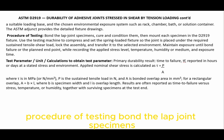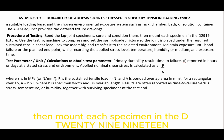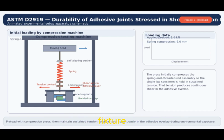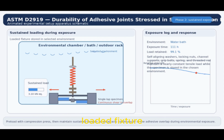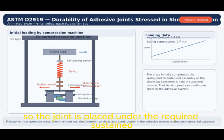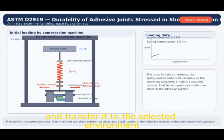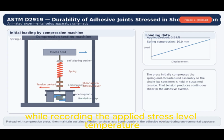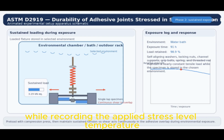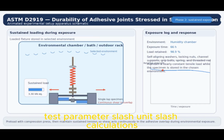Procedure of testing: bond the lap joint specimens, cure and condition them, then mount each specimen in the D2919 fixture. Use the testing machine to compress and set the spring-loaded fixture so the joint is placed under the required sustained tensile shear load, lock the assembly, and transfer it to the selected environment. Maintain exposure until bond failure or the planned endpoint, while recording the applied stress level, temperature, humidity or medium, and exposure time.